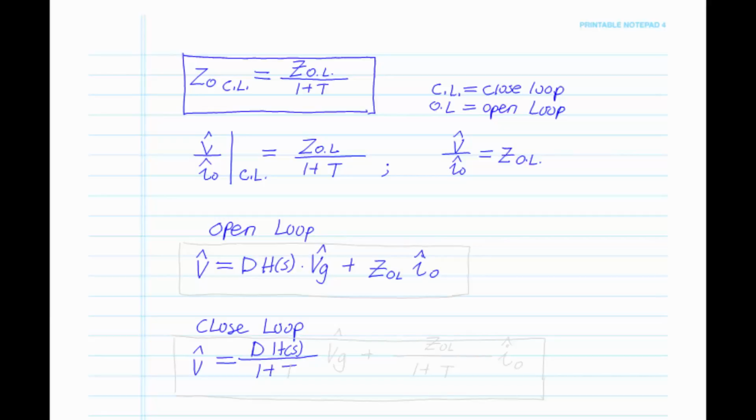And again, the best way to see that the hand analysis is going to match the simulation analysis is to do a specific example with real numbers, so that we can do a Bode plot of the open loop and closed loop, and then do the LTspice simulation with the same circuit, open and closed loop.